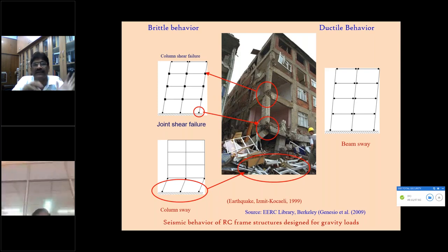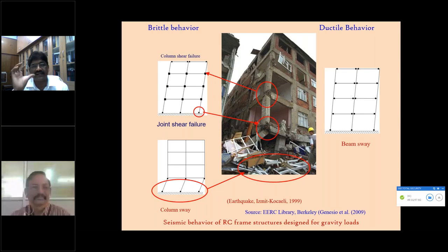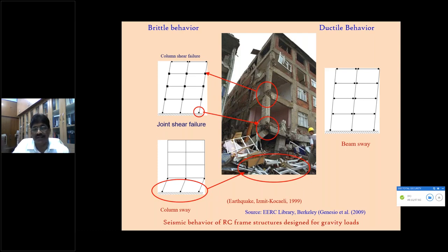You calculate the bending moments and shear forces developed at every location along the beam length, along the column height, at the junction of the beams and columns. So we will understand what are the design loads we assign, and what is happening in the real structure. Analyze that, and you see whether the structural system is safe against the earthquake loads. If the system is not safe, then you need to think about something.